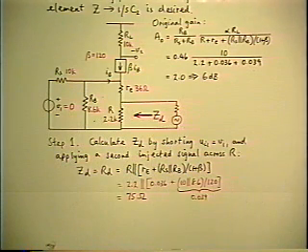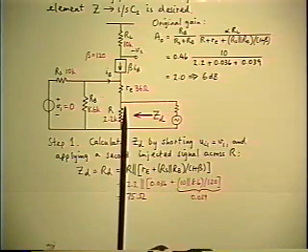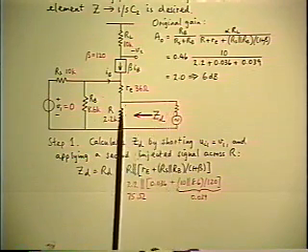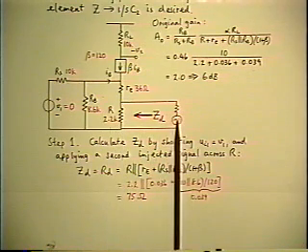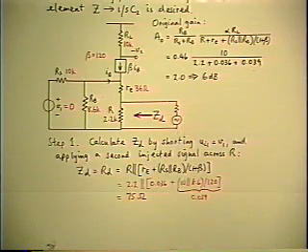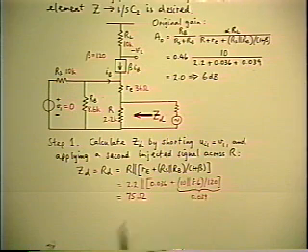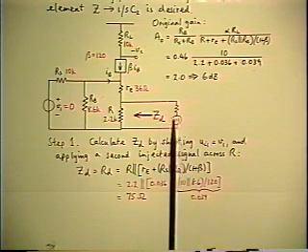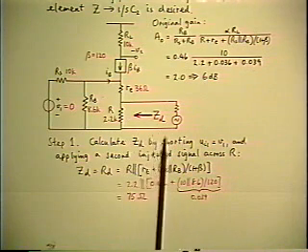Nothing new conceptually about this at all. You're simply going to calculate the impedance, driving point impedance, that exists across that resistance. Once again, it doesn't matter where that source comes from, which is why I chose a Thevenin equivalent this time, just to make it different. I don't even have to draw a source at all. But I'm drawing it anyway for the time being to emphasize the fact that there is an external source. It's what we called input number 2.